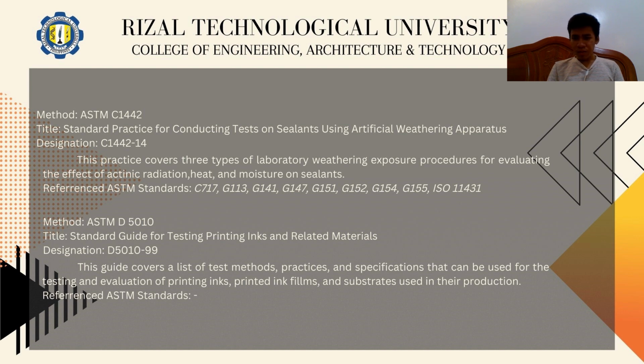When conducting exposure in devices which use a laboratory light source, it is important to consider first how well the artificial test conditions will reproduce property change and failure modes caused by end-use environments on the sealant being tested, and second, the stability ranking of the sealants.